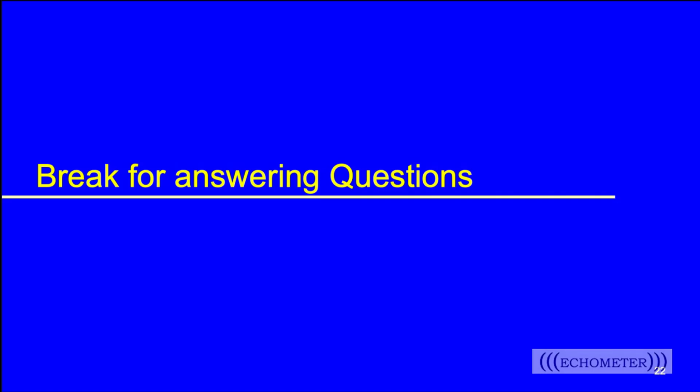Thanks. I have another question from Dan. And actually, this question already had 2 comments on the chat, and thanks to Ling and Chanel. The question is, we have been shooting fluid levels in all our shut-in wells. Most of our horizontals are on gas lift. I'm getting many fluid levels past the end of tubing, even seeing top of perforation a couple of times. Is this normal? And I would say yes.